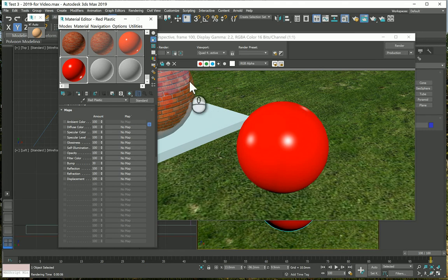And I have a picture of a cloudy sky added to the background. That's why on the bottom side I'm seeing the box and the glass, sorry, the upper part of the reflected elements is actually showing me the sky. One of the most important and yet embarrassing questions I always get is why I don't see any reflection, because you don't have anything in the scene. Most students or beginners don't add anything to the scene, and when they add the reflection factor, they just don't see anything because everything around them is just tinted black, so there is no clear effect of what the reflectiveness is doing.